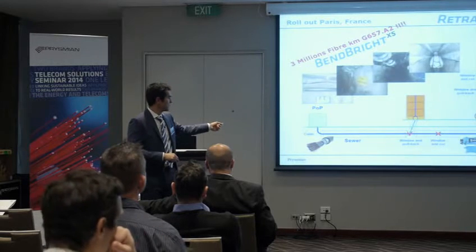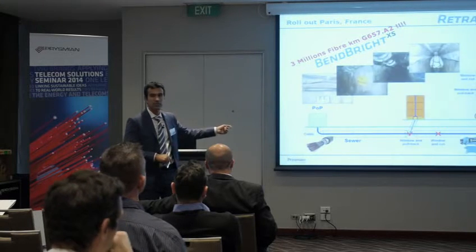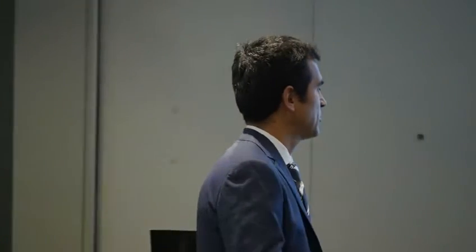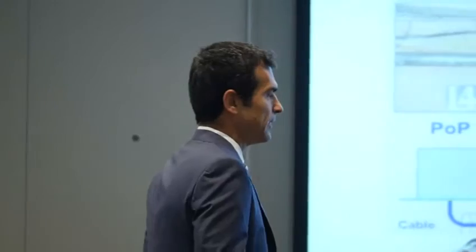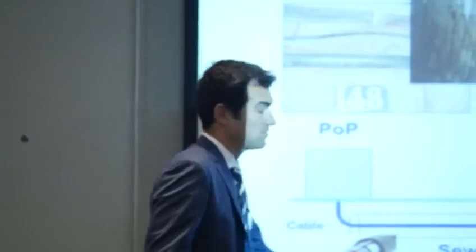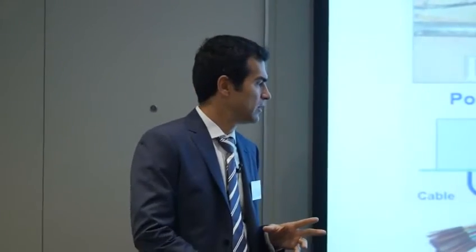And that's why they wanted a cable, as I said before, a duct with the fibers inside. If you think that this is a 720 fiber cable, which was in the region, out of my memory, of 25 millimeters, while the standard technology in loose tube would have been more in the region of 30 and more.